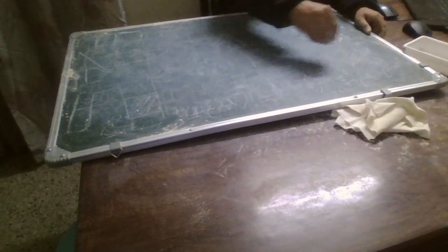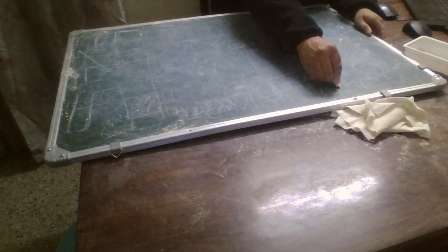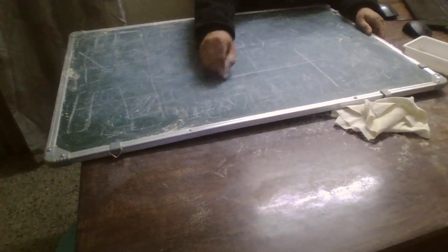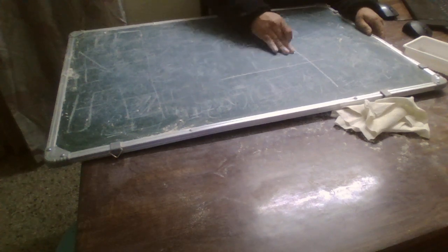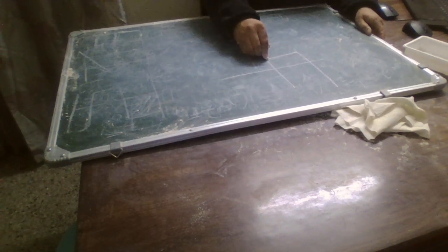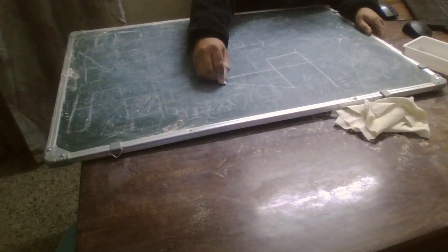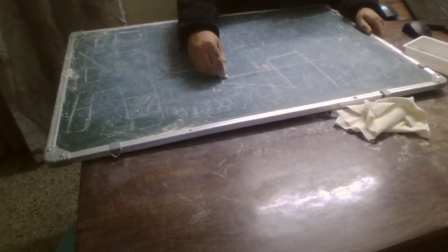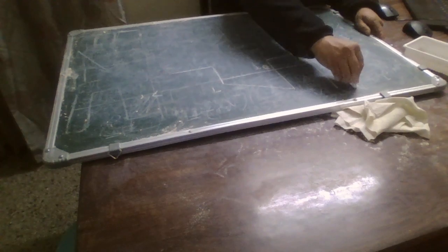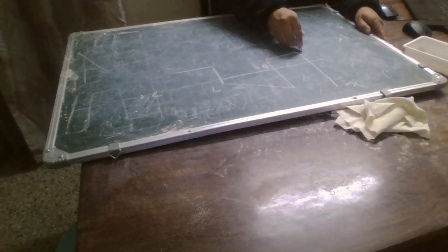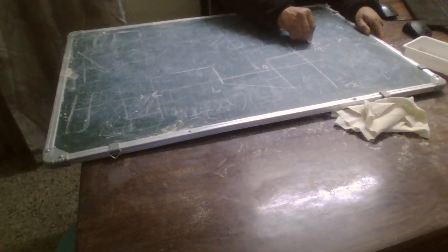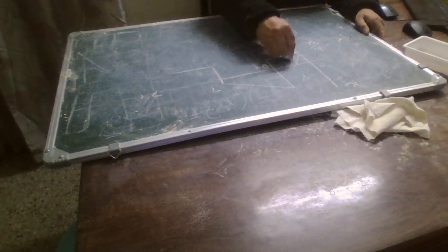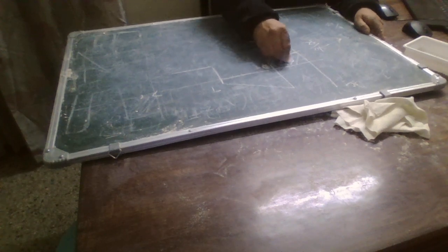Let's put the capacitor current waveform. These are straight lines, this is a slant line ramp down. This is the time axis, and this is the capacitor current, which would be minus V naught by R, because I have taken a resistive load. Again, like in the buck converter, this would be the change in the charge.